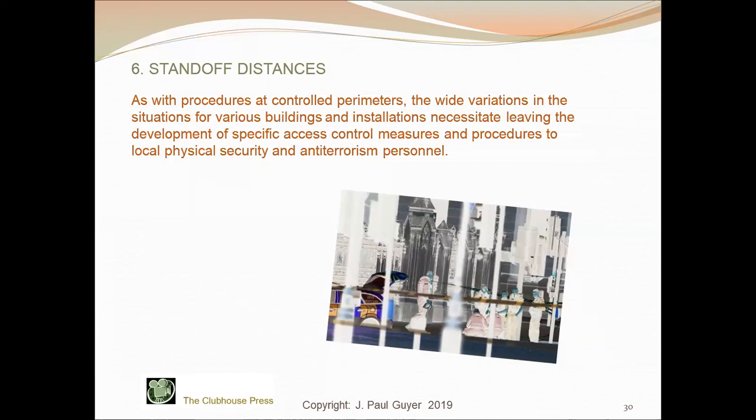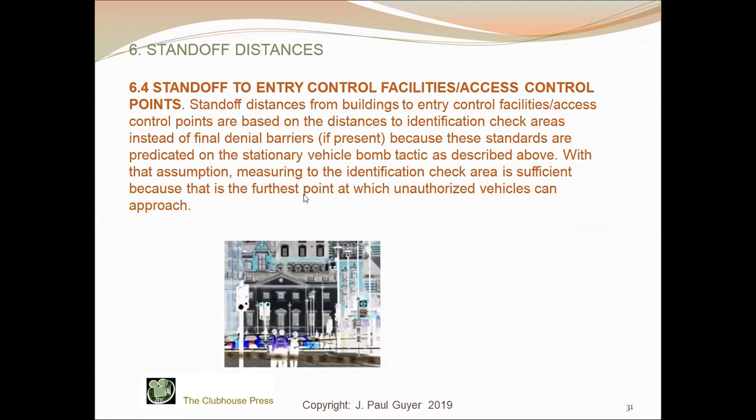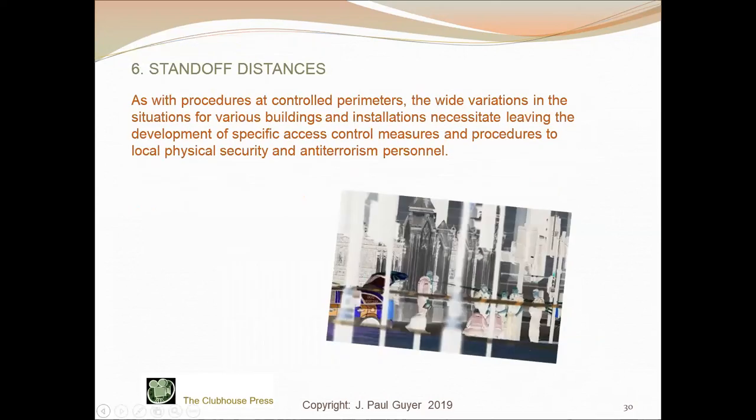The additional option for allowing parking even closer than the minimum standoff distance, as long as the applicable level of protection is met, is based on the recognition that there may be some buildings, especially in urban areas, where achieving even the minimum standoff distance is not possible.